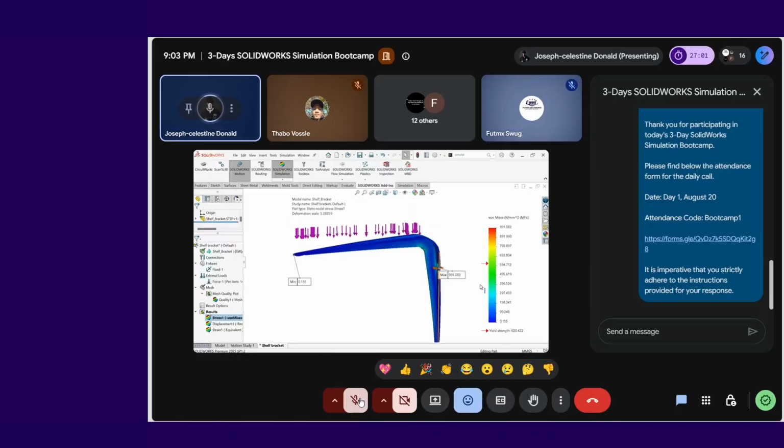Now it's easier to understand. If I ask the question, did this material fail? Yes or no? It did. The von Mises stress plot is not the real physical stress direction. It's the calculated equivalent of the stress.